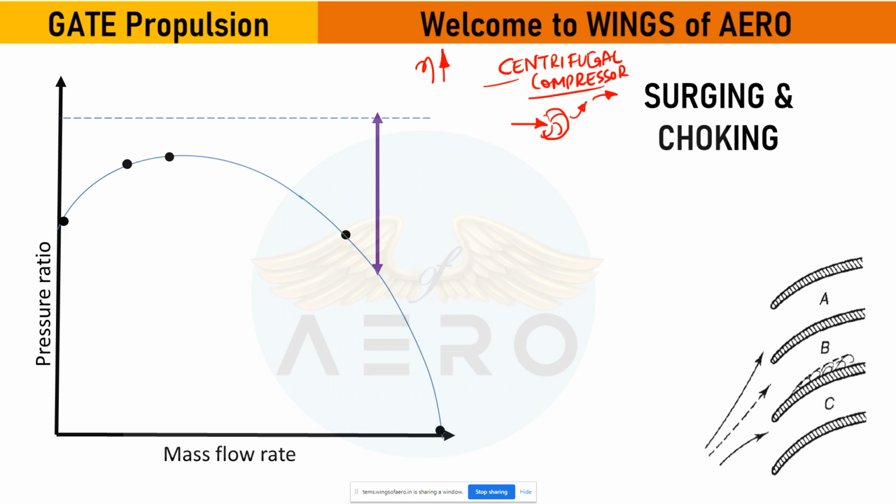Now one important fact that you need to know: the diffuser outlet velocity should range from 80 to 95 approximately meter per second. It should not increase beyond that. Okay, now why? These are part of the compressible effect.